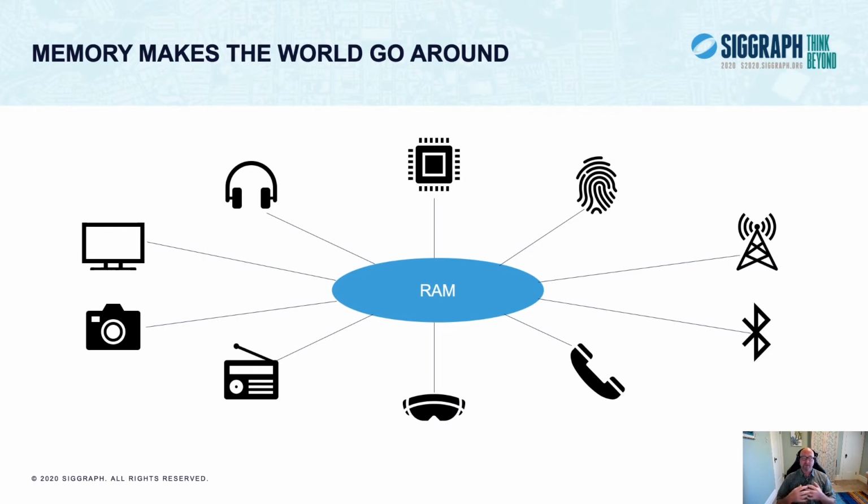So you may have something that's fundamentally a unified memory setup, but maybe a portion of it's carved out for the CPU and a portion of it's carved out for the GPU, and actually the bandwidth can work that way as well. And systems may employ specialized memory types for particular use cases. There are memories that are specifically optimized for usage by GPUs, things like GDDR memories. And then there are lower power memories that are typically employed for mobile. They're not restricted to that, but that's typically what they're developed for.